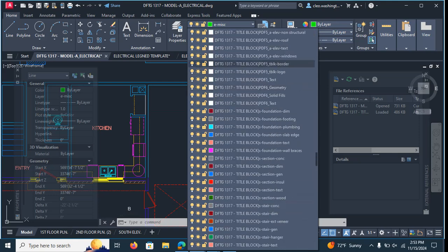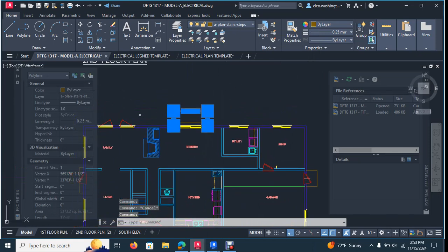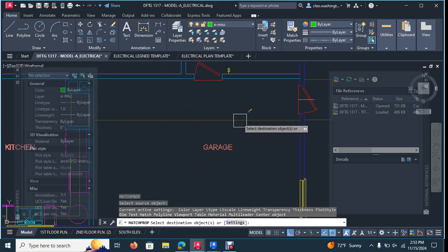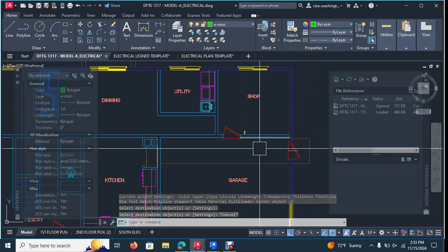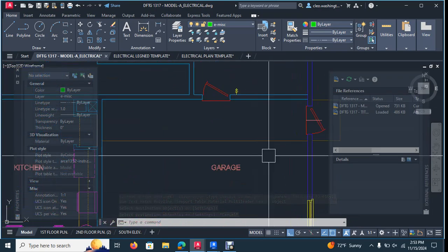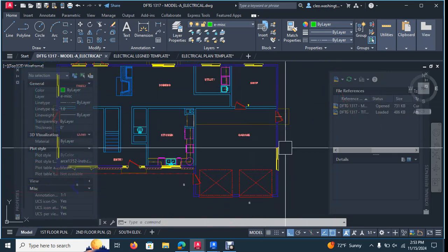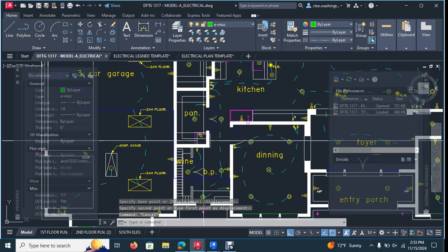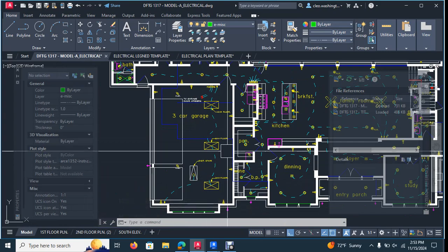And you want to put that on a concrete layer, right? So this same layer that we have here, okay? You want to hit MA. Reason being, it just gives us a guide. You don't want people to come home after having a few drinks and drive straight into the shop, right? So you have a 6-inch step up here, okay? And then you have a 6-inch drop down on this side, all right? So we'll show that on the foundation plan. When we do the foundation plan, we'll show that variation at the garage, okay?